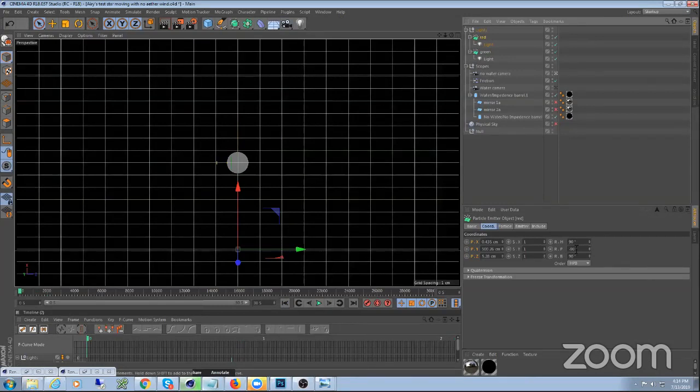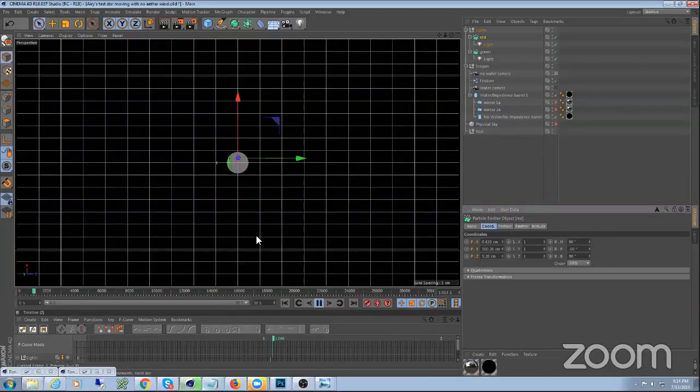And you can see the emitter is now pointing straight down again. There's no angle involved. And it's moving, as you can see. I selected it here, and it's moving towards the center of the barrel. And at exactly 1 second in time, it's going to release its particle, and that particle is going to drop down. And it's going to hit the target at 2 seconds exactly. There you go.